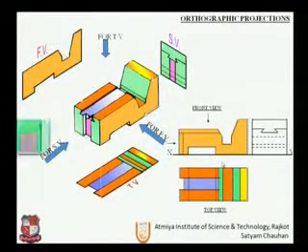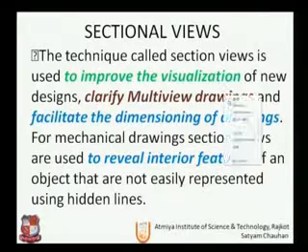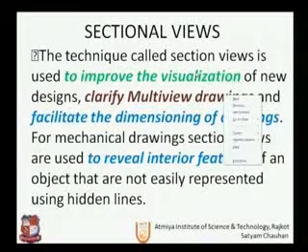And let us see the side view. So the side view will be visible here with the help of dotted lines, plus this angular slot is visible in the side view, hence it is drawn with the actual dimensions, and this will be our left hand side view. So we have completed multiple views. So far we didn't use sections. So let us see now what a sectional view is.